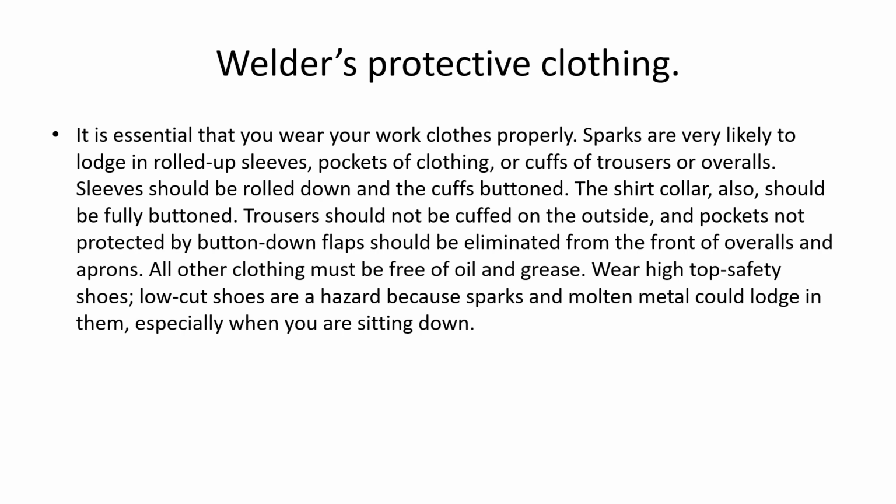So that's why we don't want a lot of places where sparks can lodge. Also, you don't want to be soaked in oil and grease when you're welding. You're covered in a combustible liquid, and it's just not going to be a good situation if you do happen to catch on fire.